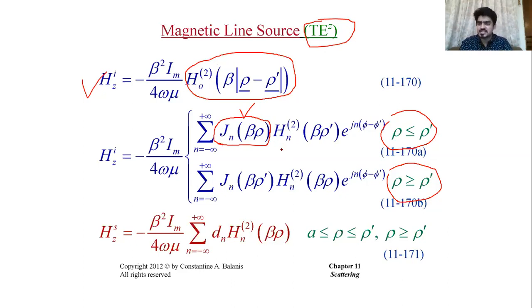Similarly, for the second region, as we saw in the last lecture, since we expect most of the waves to be radiated away in the radial direction, we usually represent it using a Hankel function of the second kind in the cylindrical coordinate system. Again, we don't use Hankel function of the first kind, because it represents waves which are incoming towards the origin of the coordinate system, here the cylindrical coordinate system. So that's why we use Hankel function of the second kind for the second region.